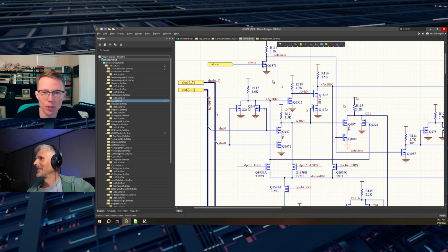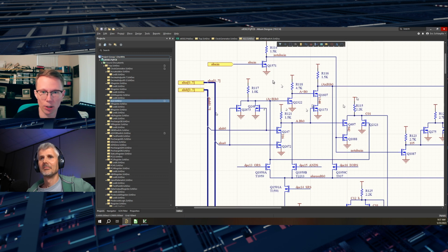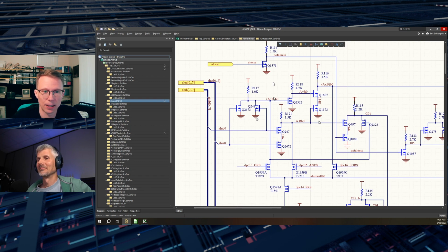So there's a couple of interesting reasons for that. Of course, the original design is all depletion mode load, for the simple reason that they just take up a lot less space than a resistor. And the saturation current of an active load like that, they set it to be something fairly low. I forget what the exact number is, but it's not very large. There's a bit more current going into these devices for the simple reason that in the fan-out, I have to drive all this input capacitance of all these power FETs. And these literally are power FETs. These are meant to be used in very small power supplies. And so the gate capacitance is fairly high.